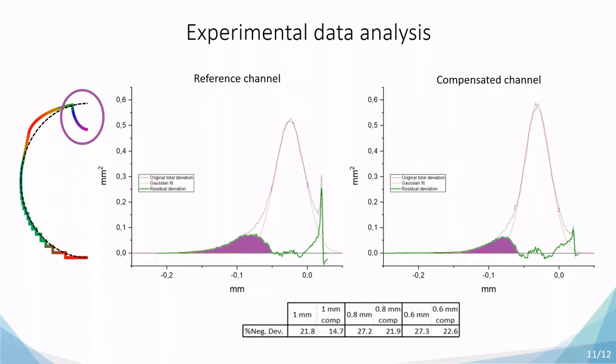However, there is a slight improvement in all three channels, and that's because by creating a surface which more smoothly goes from 45 to 0 degrees, the area here is, in a way, more supported. So the dross formation happens a little bit later and therefore is a little bit smaller.